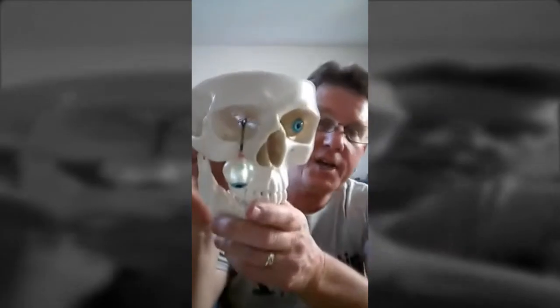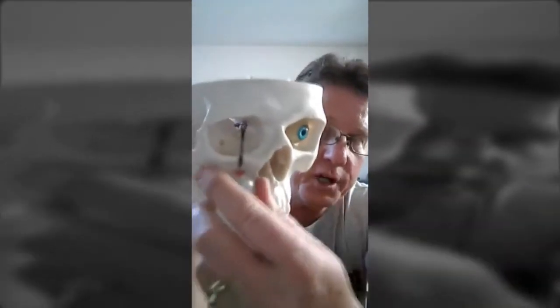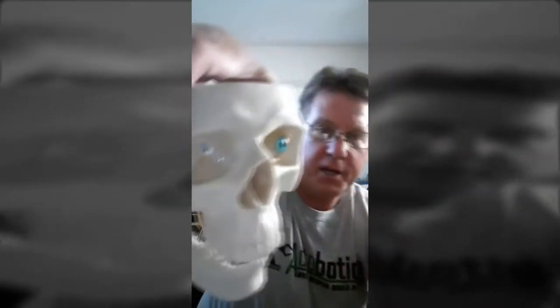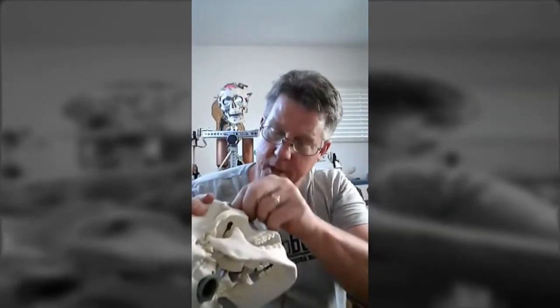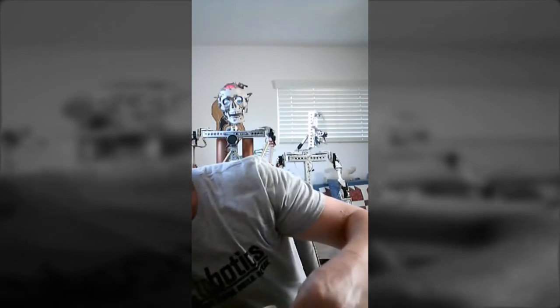Some of these eye sockets, you're going to end up with the eye like this with this connector on the other side. Sometimes the eye sockets in there are not quite big enough to put this 2-pin header in. You may have to drill that out just a little bit to be able to sneak that thing back in. But easy enough to do. Sometimes not easy to send it back in there.